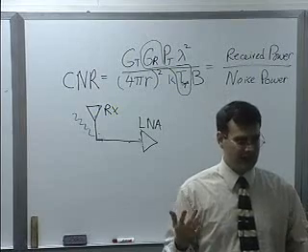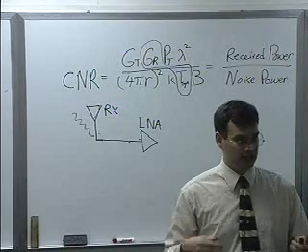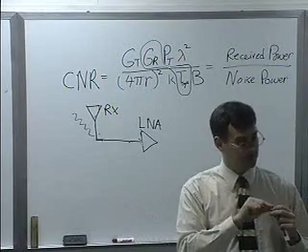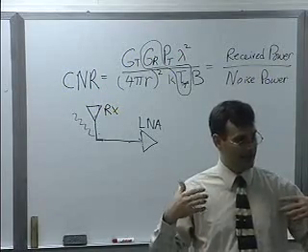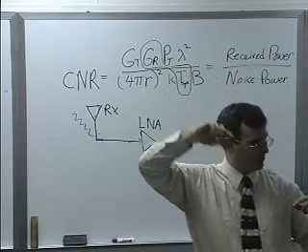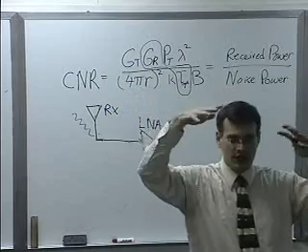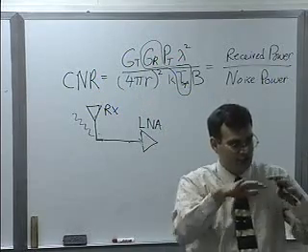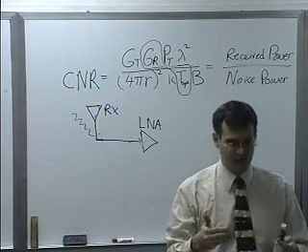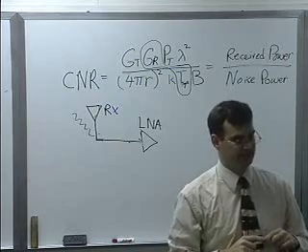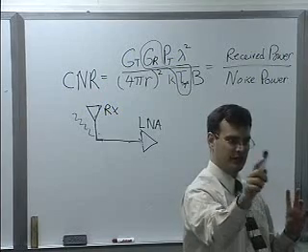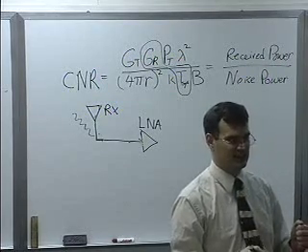But there are actually a lot of millimeter wave applications out there, like trunking from cell tower to access point, that are floating around there. And there are also some spatial users, reuse of frequency, and side lobes on your dish that will pick up other satellites using those same channels. So there are some sources still in satellite, and you still want to keep a nice front end on your receiver before your LNA. So you're right, it's not quite as much of a problem in some bands, especially when you go really high in frequencies, but it's always a good practice as an engineer to put that there.